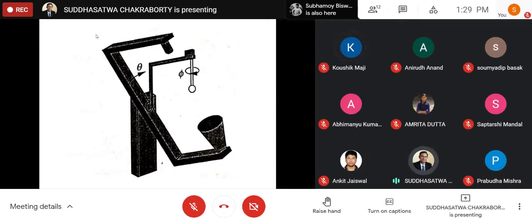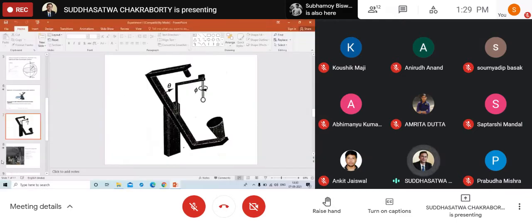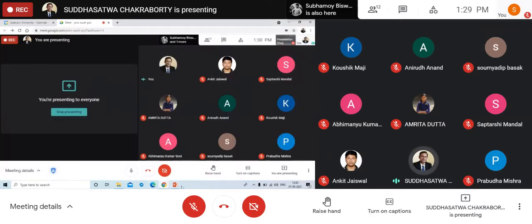Right. But it will be a really cumbersome job if we are rotating the sensor also in the horizontal plane. So that's why we allow the sensor to be rotated in the vertical plane, and let's rotate my source about its axis in the horizontal plane. So I will fix the source at 0 degree and rotate the sensor from 0 to 360. Then change the C angle to 90 degrees or any desired angle, and again rotate the sensor from 0 to 360 degrees. That's how we can reach the sphere, because that's how our spherical polar coordinate system works.